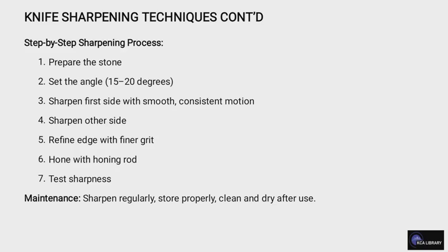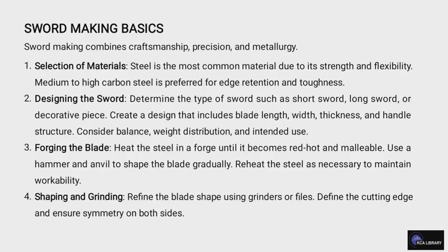Next is that you refine the edge with a finer grit. You also hone with a honing rod, and lastly you test the sharpness. And for maintenance, you need to sharpen regularly and store properly. Also, you need to clean and dry it after use.